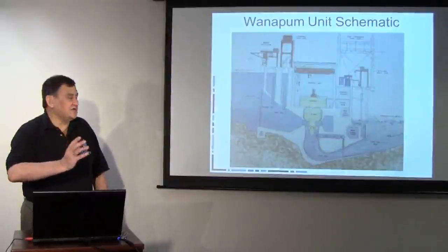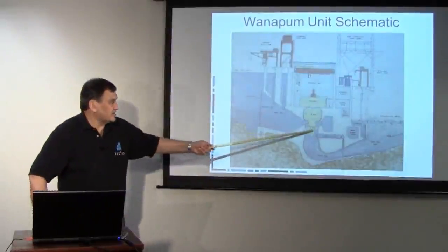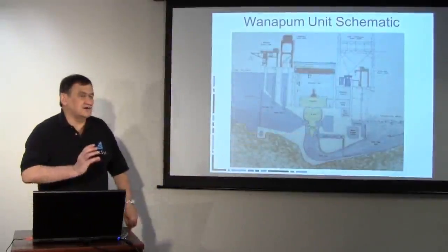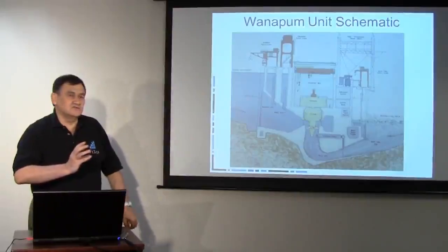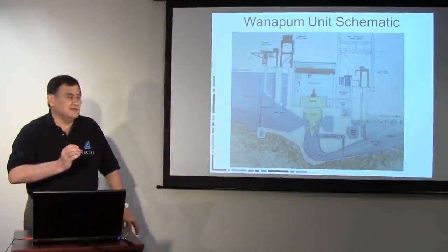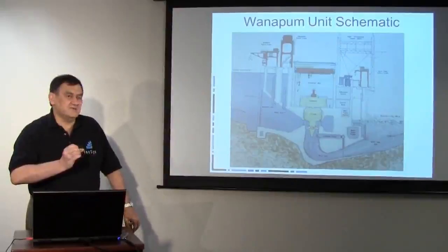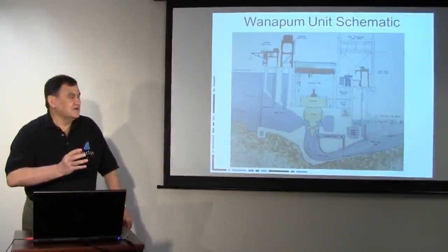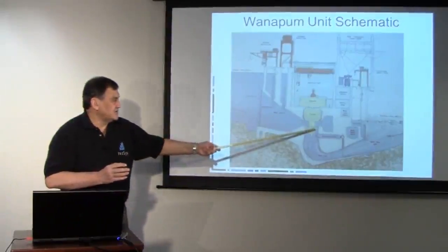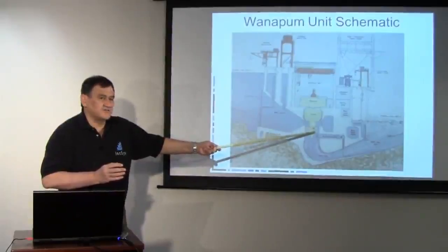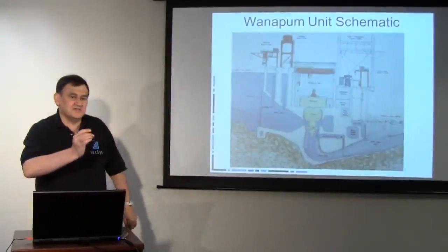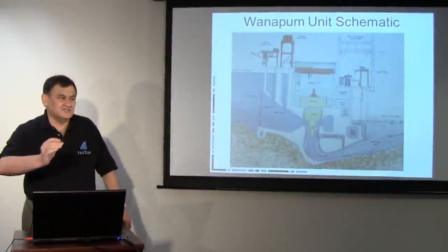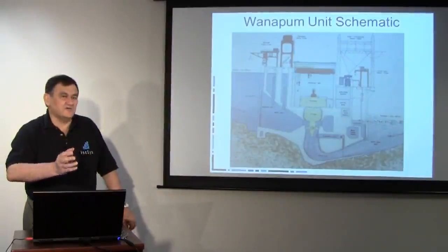At a certain speed, the water coming through here can actually turn into air bubbles, and the process of those air bubbles forming and collapsing causes cavitation. If you looked at these turbines during maintenance, you'd see a 1/8 inch channel where it had been eroded away by cavitation.